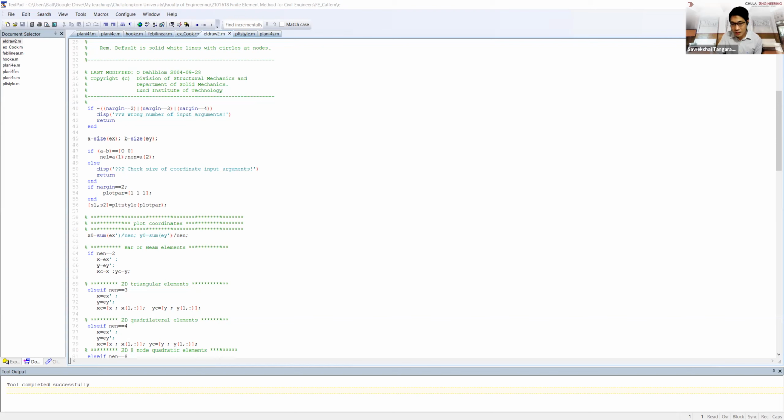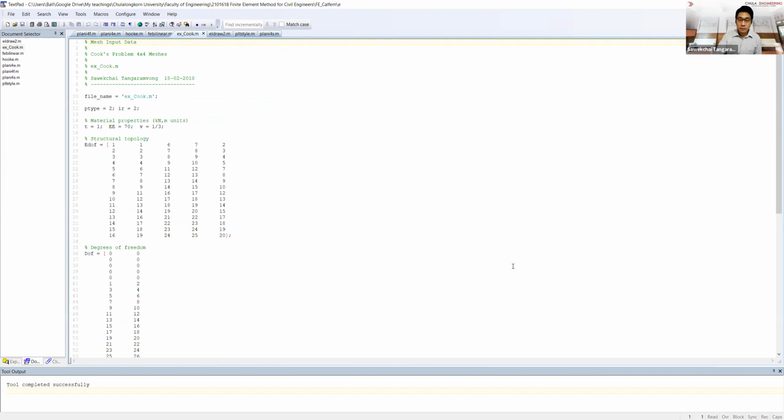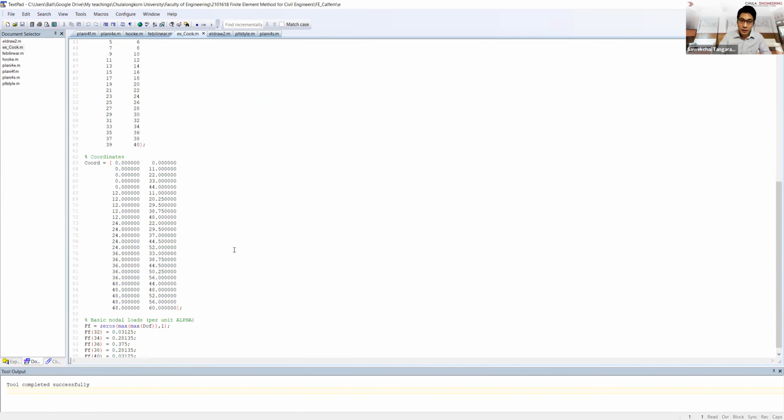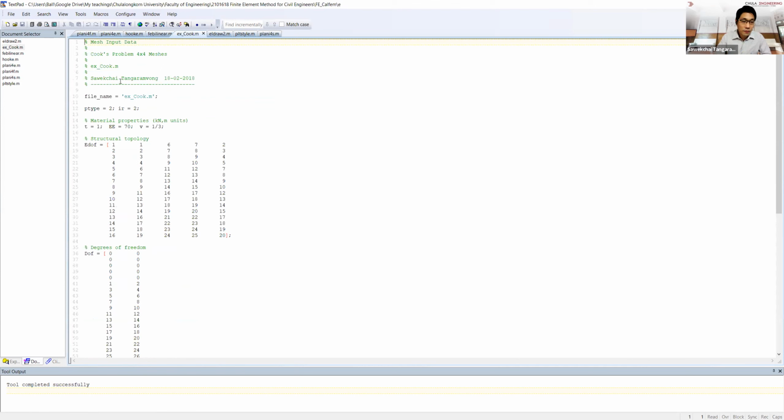But what I tried to emphasize in the beginning is to explain the problem, explain the formulation, and now we have the code. The thing that you need to know when you change the problems is that you need to put in new input. The input is very straightforward. Listen to me first. This is the Hooke law, so I put the names, right? The geometry you see already, and I wrote it for you in the note. And I say this is the plane strain, which is equal to 2 Gauss points, the thickness, the Young modulus, the Poisson ratio, and what is the most important, you have to tell the connectivity of the topologies.